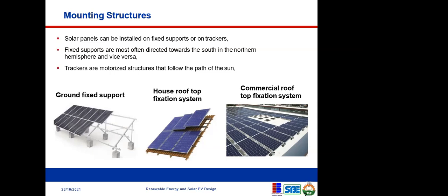So that has necessitated the need for trackers on solar PV, even though it is not common and it comes with an extra, additional cost. So when you're doing your analysis, you have to also check the cost of these trackers and see if the extra energy you're going to get by putting that tracker is viable, is worthwhile, to spend that money on. So that's why it's important we do all of this analysis in our design stage to know what could be included in our design.